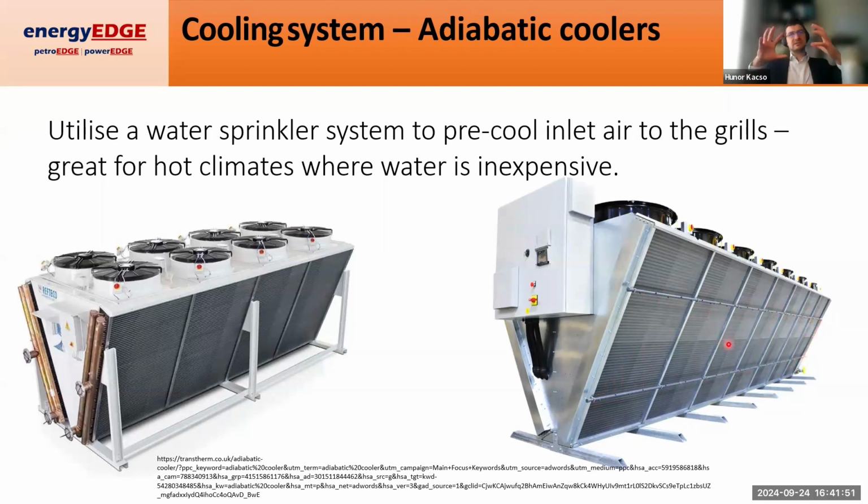What this does is the air drawn in through the inlet grill will be pre-cooled, because as you're spraying this water into the inlet air, you're going to pre-cool the air.